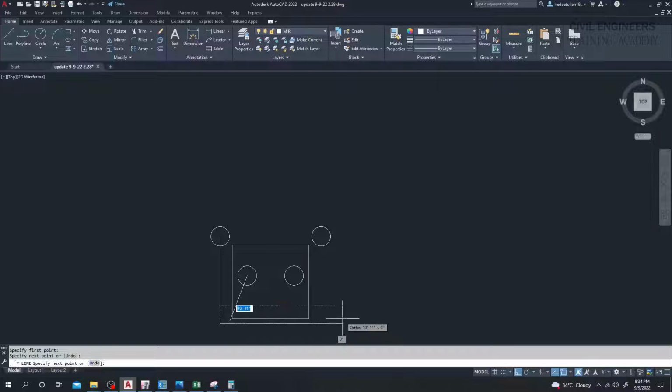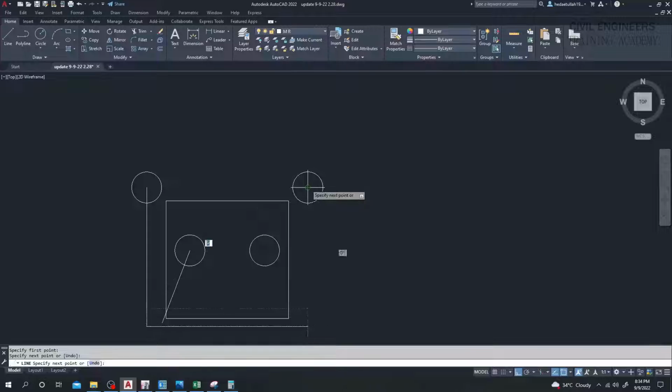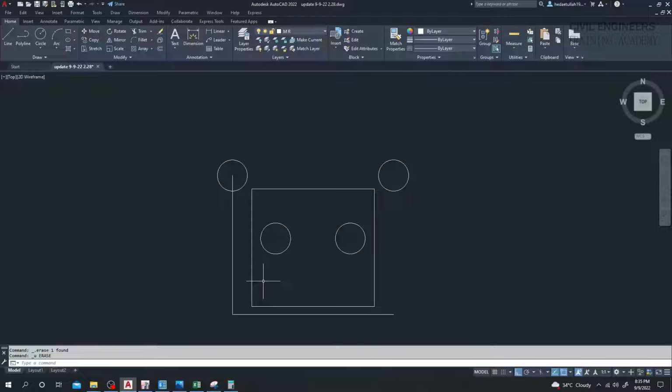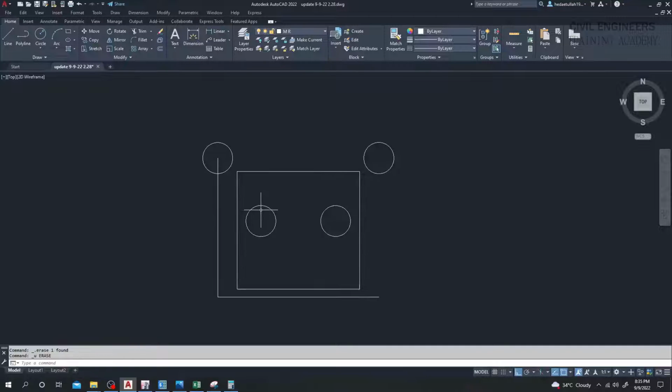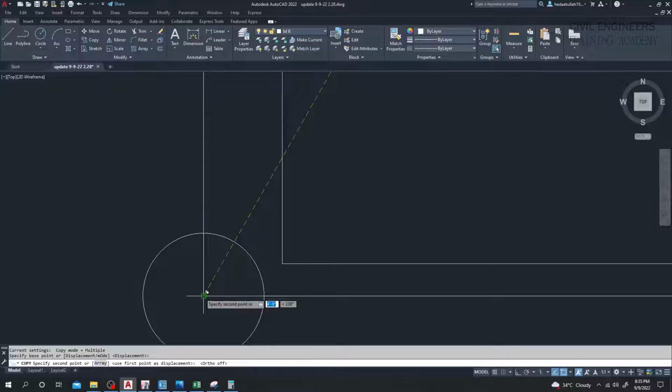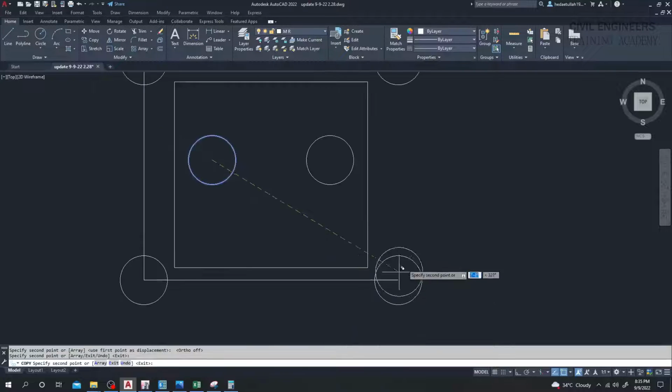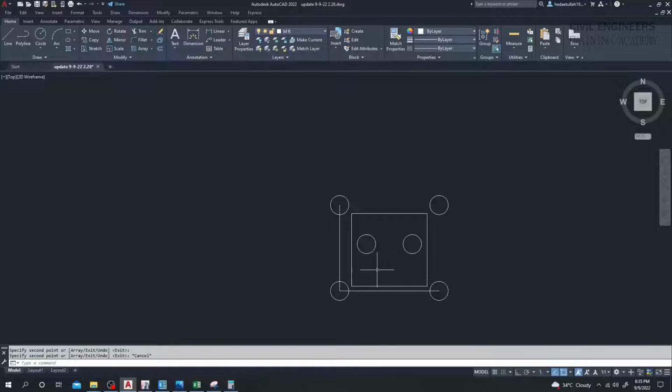Similarly, now I'll just go in that direction with respect to that one. I'll draw another point. So we have found all our pile locations, right? I'll delete that one. Sorry, I need that point also. Now I'll place pile here. Stop ortho mode. Here we need one pile. Here we need another pile. Just done. We have placed all our piles actually, right?